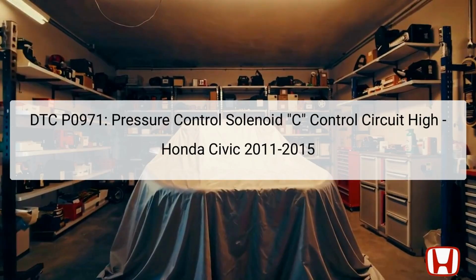The Diagnostic Trouble Code, DTC P0971, pertains specifically to the Honda Civic models from 2011 to 2015 and indicates a problem with the Pressure Control Solenoid C control circuit, categorized as a high-condition error. This code suggests that there is an electrical issue rather than a mechanical fault in the continuously variable transmission, CVT.